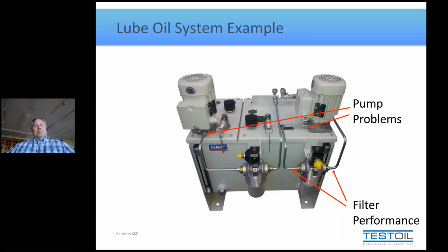So what would we like to do next? Maybe we'd like to change the oil based on condition. So we want to know if the oil is suffering, if it needs replenishing, replacement. So where we get that data would be by sampling out of the reservoir. Now at this point, it doesn't really matter if it's the top or the bottom. We can sample any point in the reservoir and we'll have enough information to know when to change the oil.